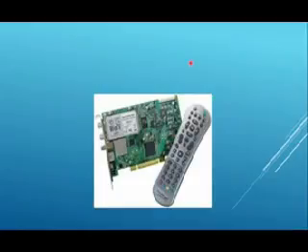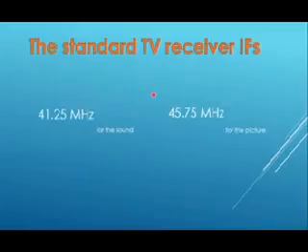The signal from the antenna or the cable is connected to the tuner, which consists of an RF amplifier, mixer, and local oscillator. The tuner is used to select which TV channel is to be viewed and to convert the picture and sound carriers plus their modulation to an intermediate frequency. Most TV set tuners are packaged in sealed and shielded enclosures.